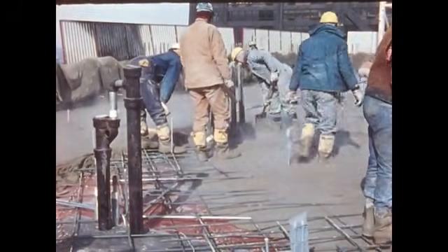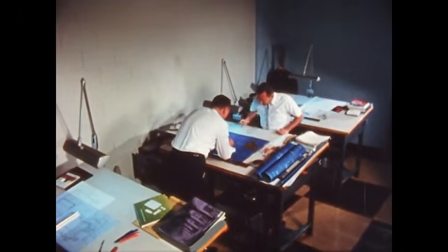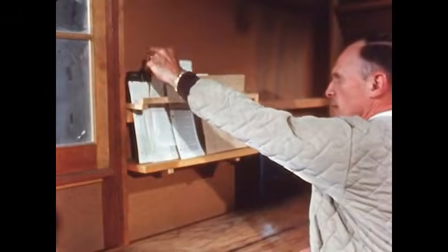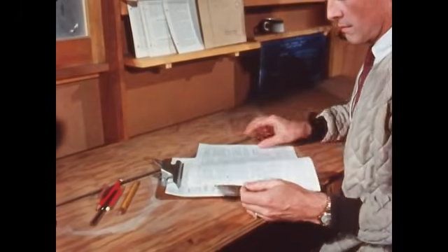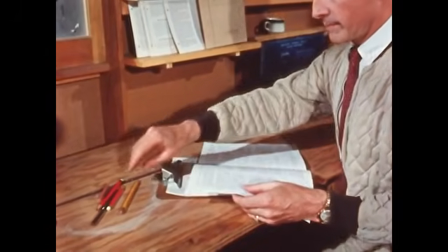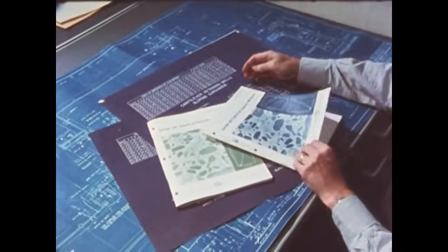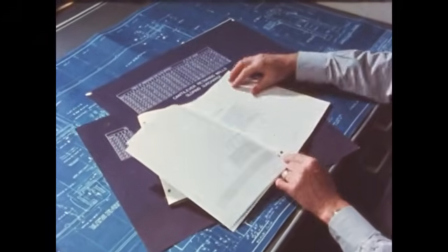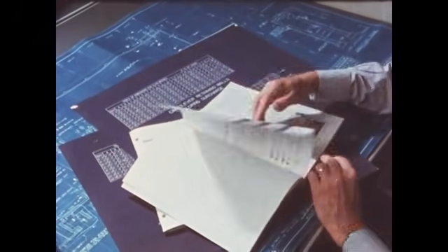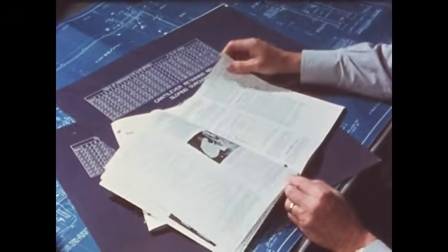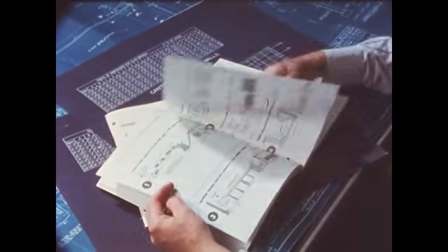The qualities desired in fresh concrete are established by its intended use in service. These are included in the drawings and specifications by the architect and engineer. They are translated by the contractor's concrete supplier into economical quantities of properly proportioned materials that go together into a workable mix. Fortunately, the quality controller or concrete technician has manuals prepared by the Portland Cement Association and other agencies, which contain tables and charts to help him set up trial mixes of concrete to meet any requirement. The following example illustrates the fundamentals of quality concrete mixture proportioning.